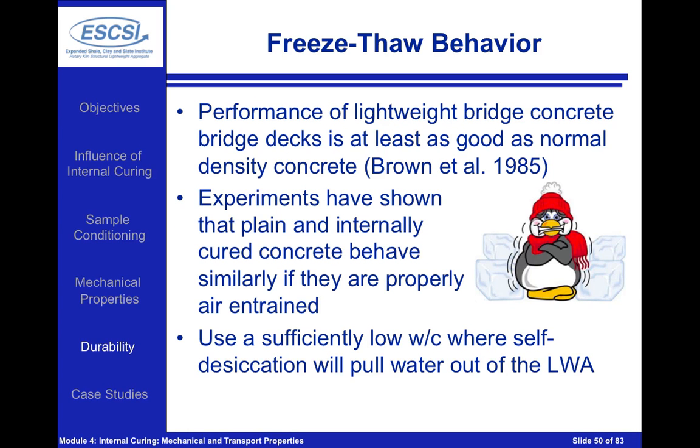To push in a little bit more on the freeze-thaw behavior, the performance of lightweight bridge deck concretes is at least as good as normal density concretes, and this is from a study from Brown. Experiments have shown that plain and internally cured concrete behave very similarly when they're exposed to freeze-thaw if they're properly air entrained. The whole idea here is that if you've properly air entrained your concrete, whether it's a plain concrete or an internally cured concrete, that concrete is going to be freeze-thaw resistant.